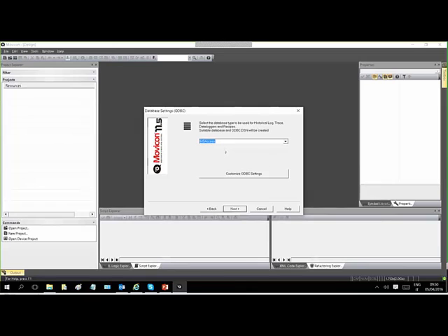Movicon will generate an MDB file. This engine is available in all the Microsoft operating systems, so we can go without touching this part for the moment. We just know we will store, for example, our logs, all the alarm events inside an access file. Data logger is the folder that will drive the database interface for your field variables. We'll discuss these properties, these important features, during the second part of the webinar.